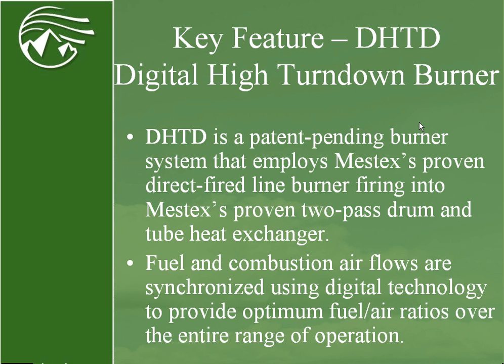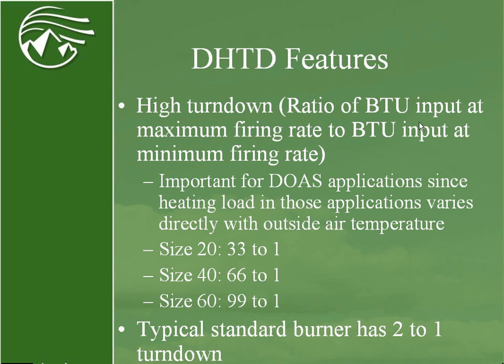So both the airflow and the blowers and the heating is all synchronized, and they can actually turn down up to 99-to-1 on some of these systems. So you've got a high turn down. It's the ratio of the maximum firing rate of the BTU input to the minimum firing rate of the BTU input. That's your turn down ratio.